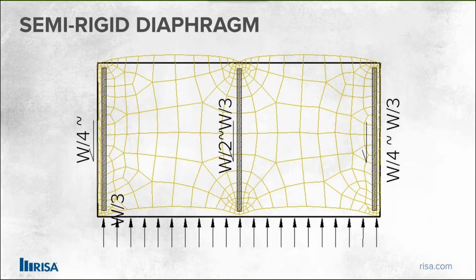In this case, we're actually drawing in the diaphragm using plate elements. And as we apply that load, we can see the load gets dragged through the diaphragm. You can see I meshed those plates and you can see them deflecting. That deflection is carrying those loads, and there are forces and stresses in those plates that help distribute the loads to the wall elements. So you're going to see roughly the type of load.